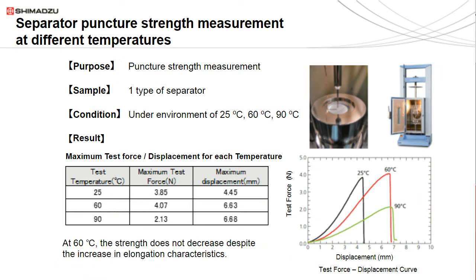Next is an example of the puncture strength test of a separator material. Since separators are packed densely inside the battery, it's necessary to determine the strength of the separator against a puncture to prevent it from being punctured by electrode materials or during manufacturing.